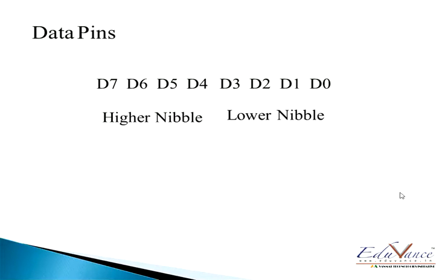Now let's take the example of serial and parallel communication. What do you think is the advantage of serial over parallel? Less number of wires, and disadvantage would be it is slower. So in our case, I won't really say that this is serial and parallel, but if you use a 4-bit data transfer mode, then your communication might be a bit slow, but you will be saving a lot on your pins.